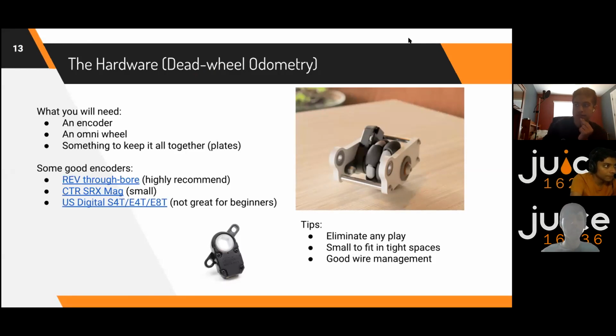And then we needed to create a pivot system, so that if it came into contact with an obstacle, it won't just hit the obstacle, but instead it would pivot and move up and respond to the environment. So we would have a standoff going through the module, and that would allow it to pivot on that axis. So it's important to include that or a similar kind of system, so that you can have that pivot for your module.